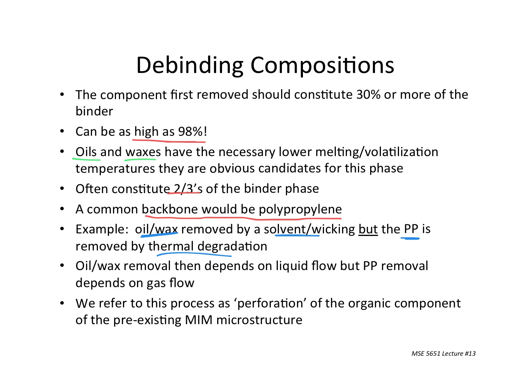All right, so you can just suck this liquid out, and it says oil. It's relatively high viscosity oil, trust me, but it is an oil. That comes out easily when it sees these porous surfaces into which those liquids can flow. And so we have a difference in that the wax removal is liquid flow, polypropylene removal is gas flow. All right, different temperatures, different phenomenon, but when this is present in very small amounts, you don't have to do the whole force flow thing. You don't have to pressurize your component anymore because it's sitting there and it's wide open pore spaces. It's easy for it to come out, and there's not much of it. Okay.